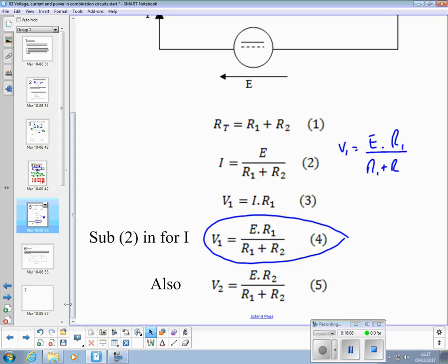Okay? So if you look through electrical principles books, you're going to find that they talk about the voltage divider rule, and it's a quick way, where there's only 2 resistors, to get the value of the volt drop across one of them. I think that'd be a bit more messy when you start to substitute in. Yeah, you're better off just to use that for the 2 resistor voltage divider.